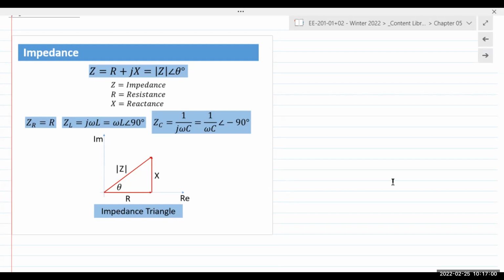Same thing for a capacitor. If you apply a constant DC voltage, it charges up the capacitor. When the capacitor reaches full charge, it behaves like a, anyone? Open circuit. No more current can flow through. The voltage is maximum, but current goes to zero. But what happens when you start to change that voltage?